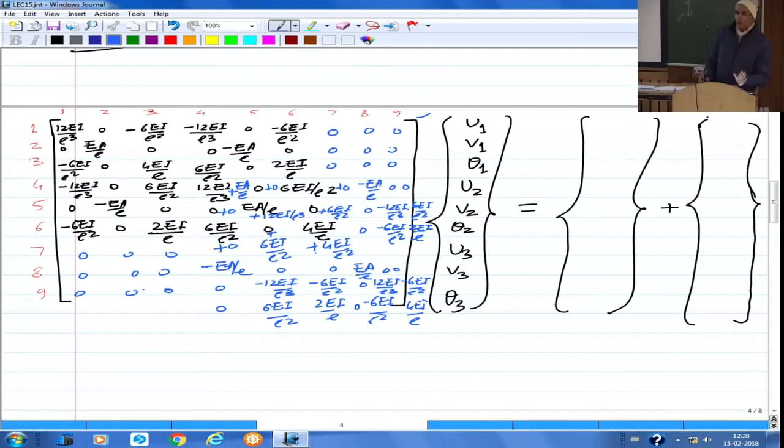It's the same as what we were doing earlier. Only thing is now at each node you have 3 degrees of freedom, and total for the element 6 degrees of freedom, and accordingly you are doing the assembly. Of course you should also be able to assemble if I make the third node as second and second as third, so that switching over you should be able to do.